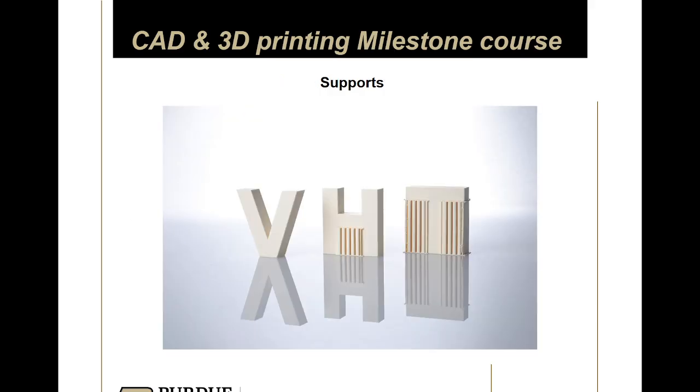Here's another example of supports. You can see here that the H may not have needed supports because there's two beams and an overhang in the middle. Some printers can bridge across that gap, but depending on how long it is, it might be a little bit more difficult. I'll talk about bridging in a second. That T, there's nothing supporting the ends of those T's, so printing a support in this direction is kind of necessary. Would anyone have any recommendations for the person printing this to remove the need for supports?